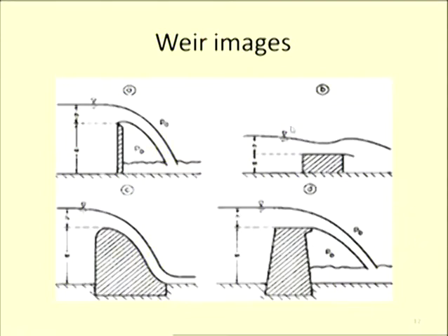and the nappe is generated like in the sharp-crested, but the water jet is touching the total crest here but not damaging the downstream side of the weir. So that is the difference. So these structures are constructed in a channel, river or anywhere for measuring or abstraction of the water.